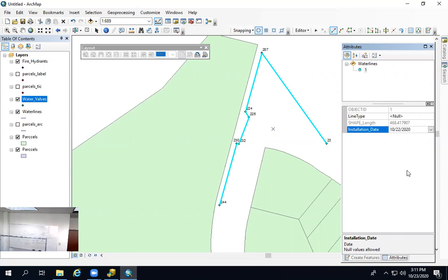Okay. So guys, we added now a date. What else can we add? The line type, and that's one important thing I need to add. Let's say this is a main line. So you go here, and I add M for main, and this will be the first record in my attribute table in this layer. Let me show you some other stuff. So snap and copy what you did in your Word.